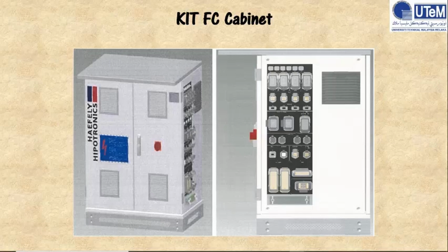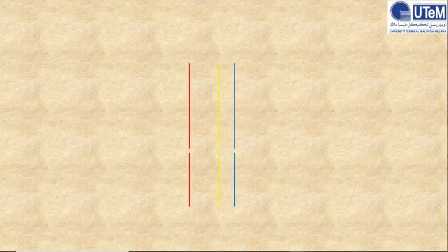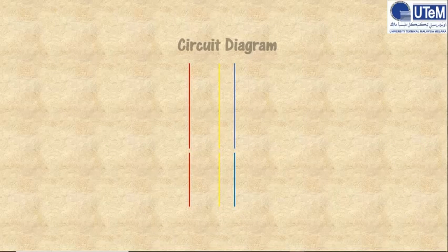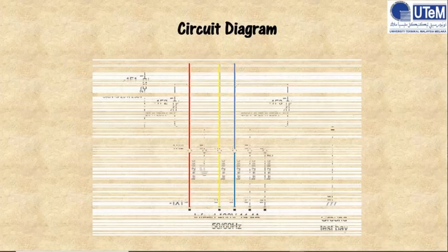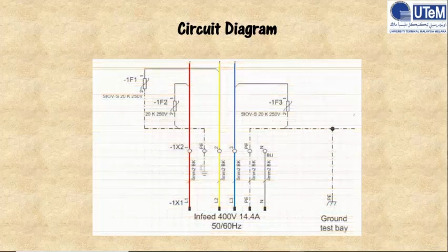At the bottom connection, we connect the 5 core that was named earlier, and at the top of the power block terminal, there are 3 black cables. Of those 3 black cables, 2 will be connected to the internal transformer, and the other one will be connected to the current transformer.